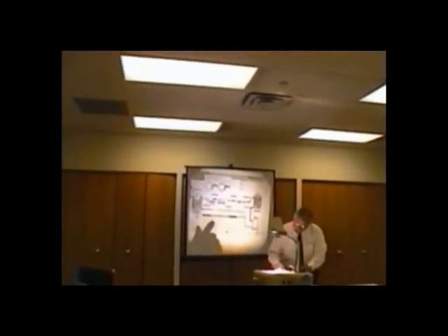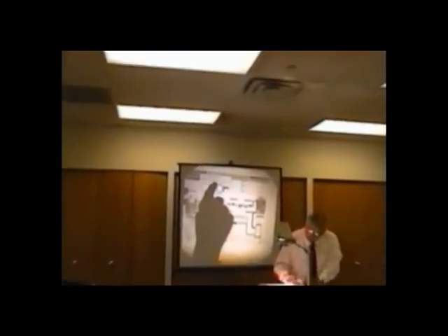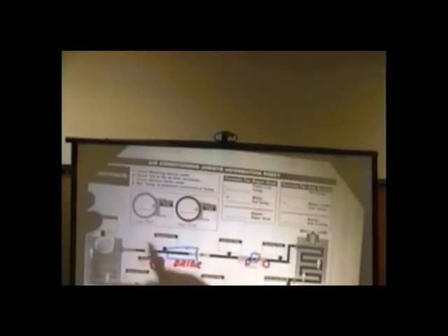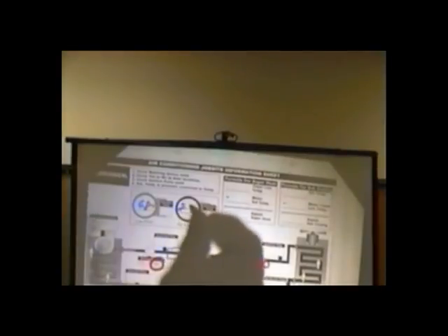All right. Let's go back and let's bring the job site sheet up again. And over here it says saturation temperature is pressure converted to temperature. So let's do that. And I'm only giving you this as an example. Let's put down our low side pressure. Let's say it was 68 psi. And our high side pressure, wasn't that 278? Yeah, 278. And so for superheat, the vapor line temperature, we said we had a suction line temperature of 50, and we had a saturation temperature of 40, and that gave us 10 degrees of superheat.